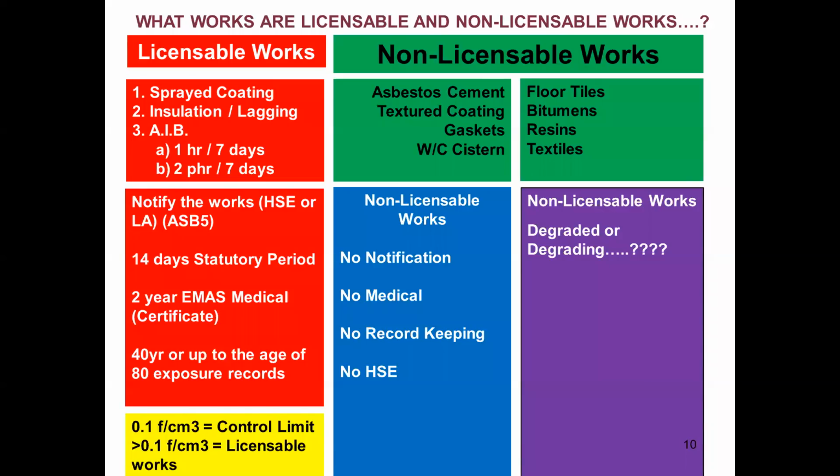A good example that would be textured coating. Drilling holes in textured coating is classed as maintenance works, but if we started to use a water-based solution such as X-Tex, texture removal, or steam to break the matrix down, then we would be degrading the product. Therefore, that work would fall under the purple column. There is some future guidance planned by the HSE to further define this, but there are some good clear definitions in L143.